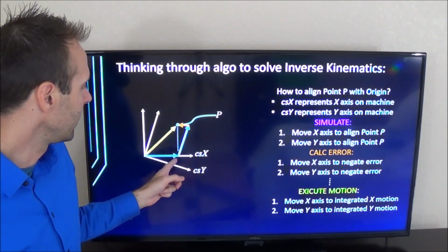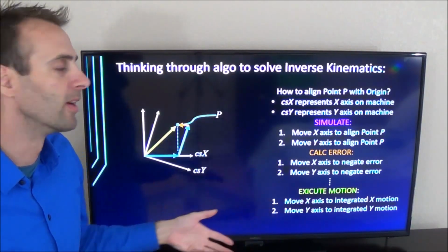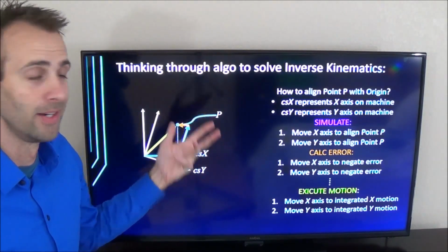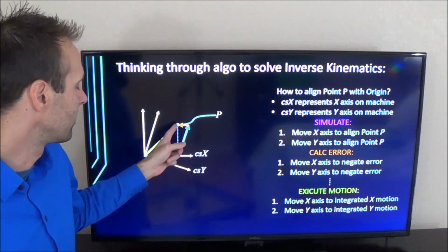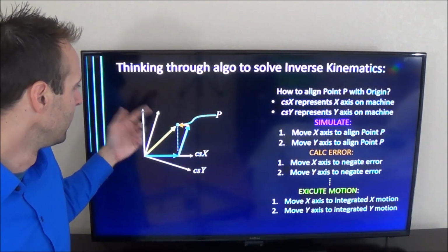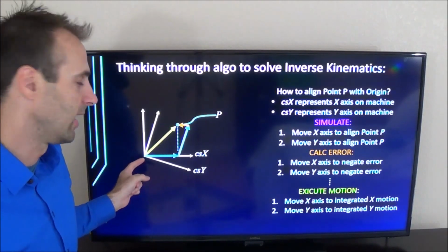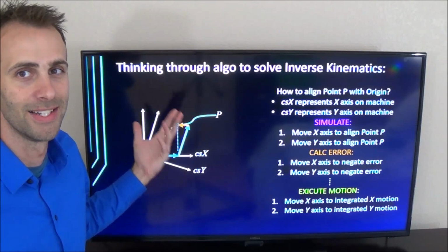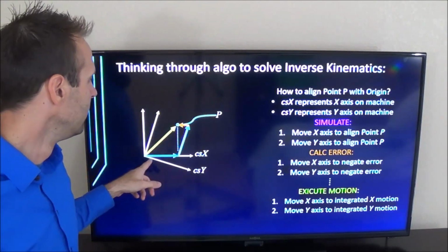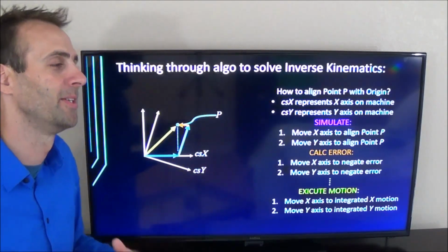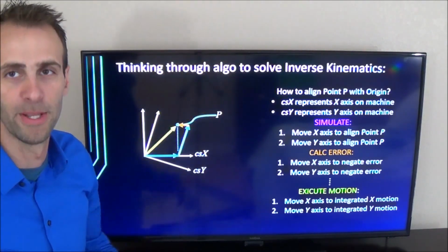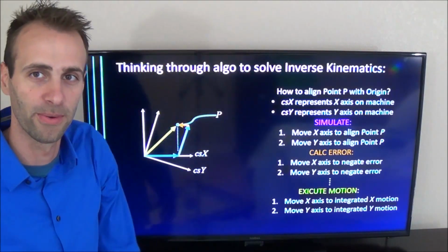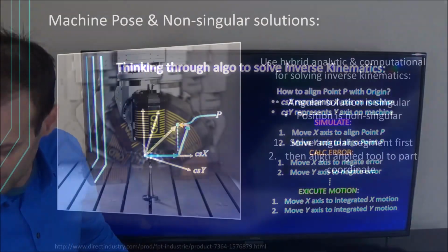And like I said, if your machine is more right than wrong, you're not talking thousands of iterations, you're talking like 3, right? So even in this crazy diagram here where it's like a 15-degree error or something like that, the second one gets me really, really close, right? So again, you're talking maybe 10 iterations per point, and I don't know, maybe there's a million lines of G-code or whatever, but it's not crazy, right? For a computer, it'll blow through that so fast, even a laptop.